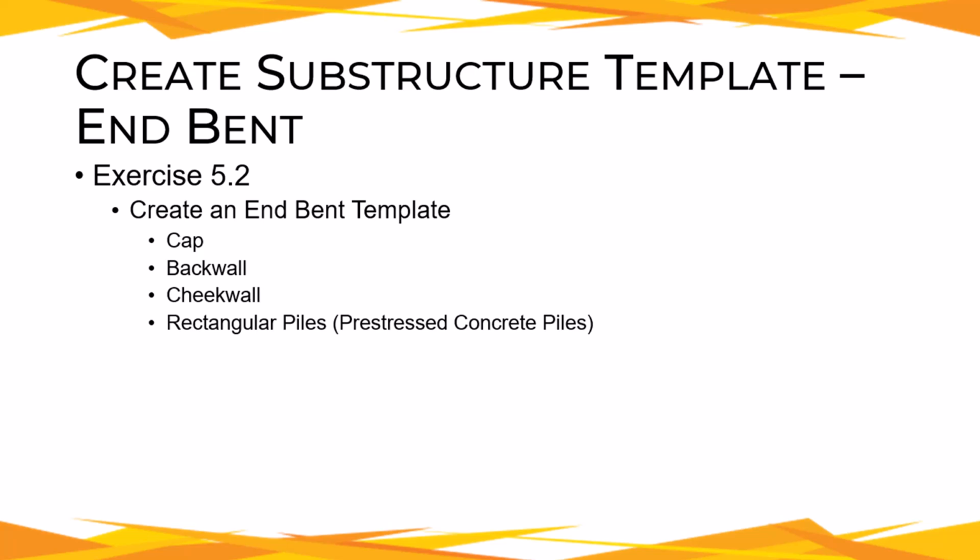The OBM end bent templates will work fine for end bents with no skew, but they have limitations if they are on a skew. Mainly, the cap and the back wall cannot model the breakbacks, otherwise known as the kinks in the corners or at the ends to accommodate the skew. Even if the end bent is on a skew, the out-of-the-box templates can still be used for preliminary design to check horizontal clearances or other things you need to check.